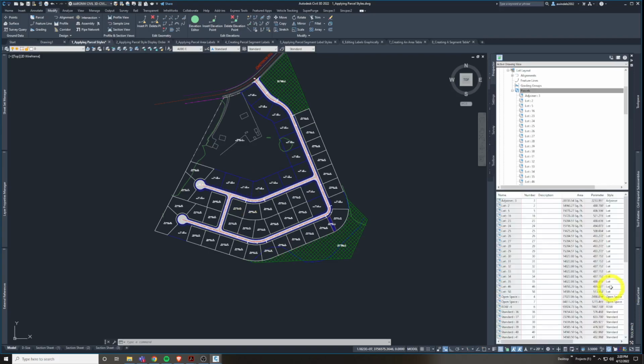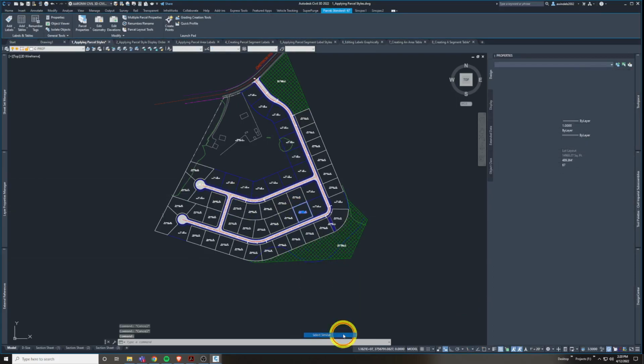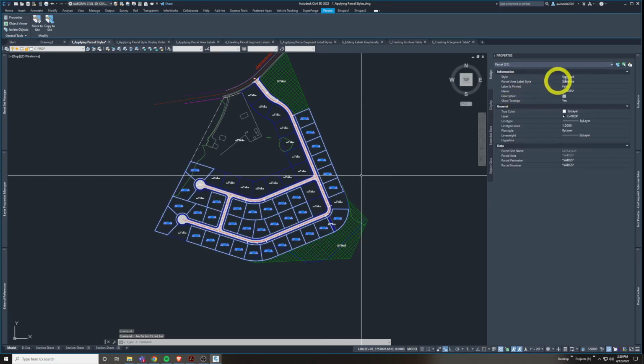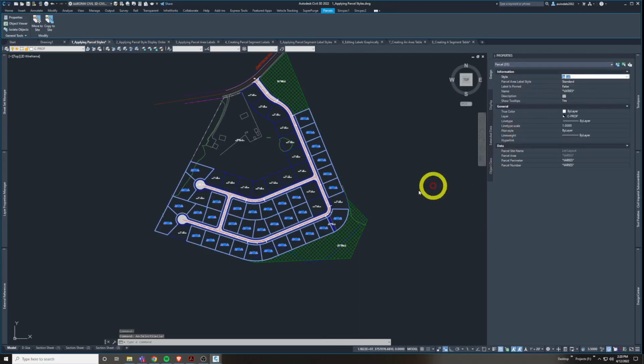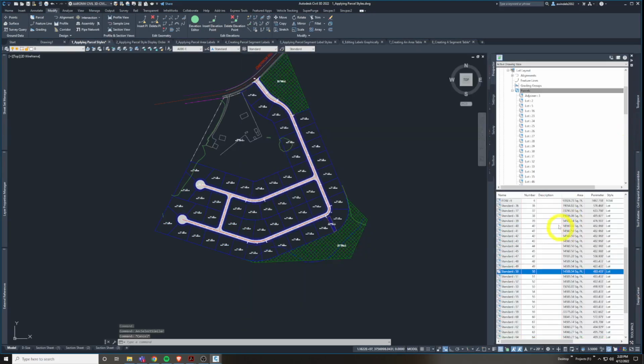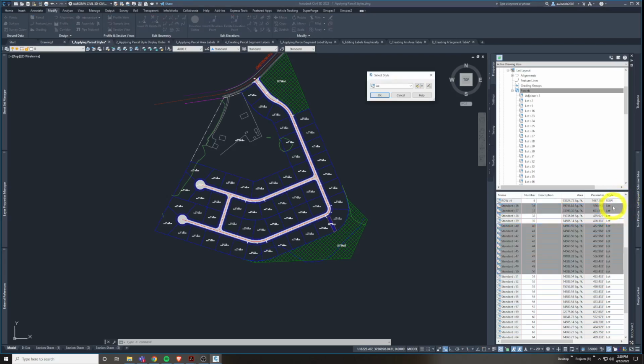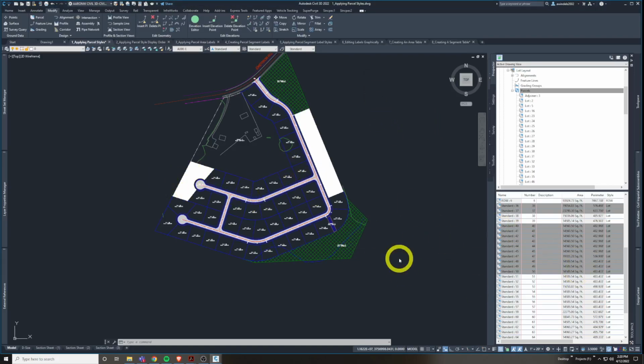It takes a minute, there they went. So that's kind of a cool trick, but I prefer honestly to have one picked and select similar and then change them this way. Of course, doing it the way the book shows lets you more surgically grab them. You can grab just the ones you want, a couple outliers, and you hold shift and keep left clicking. On the style column is the key. Right there, you can surgically pick exactly which ones you want and change them to something else, which is pretty cool.